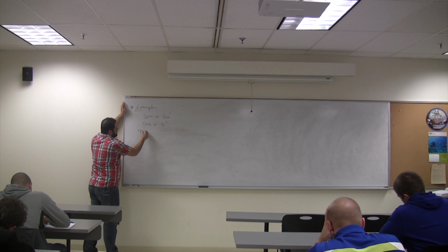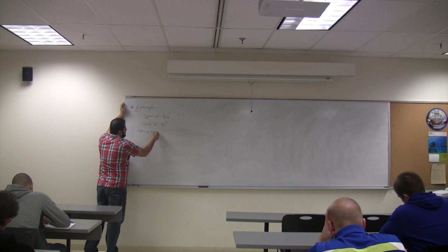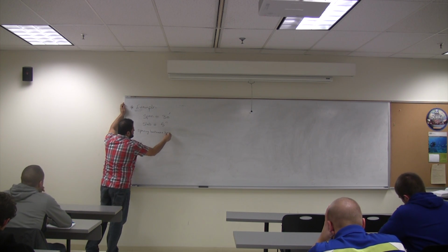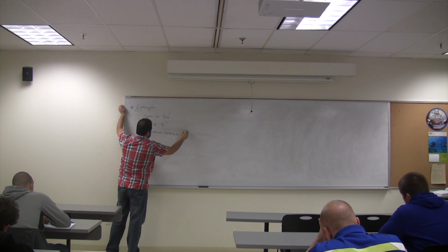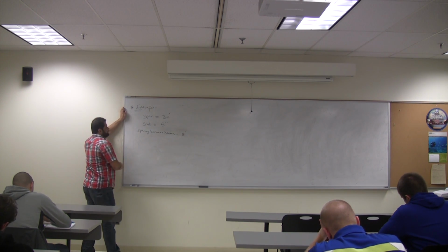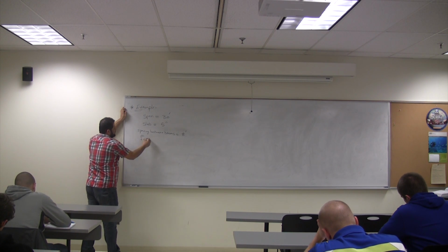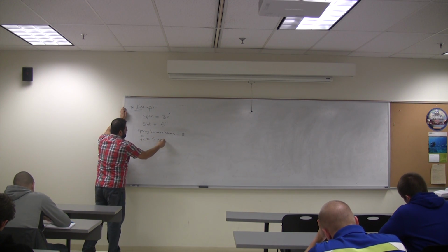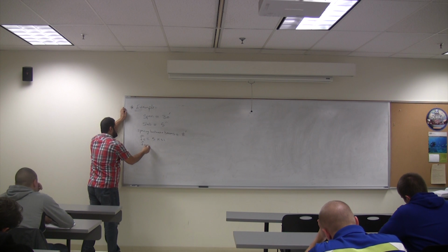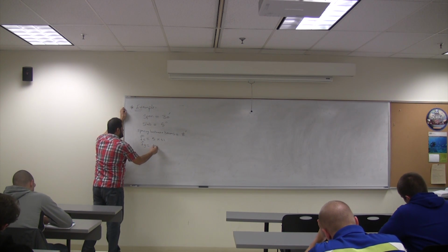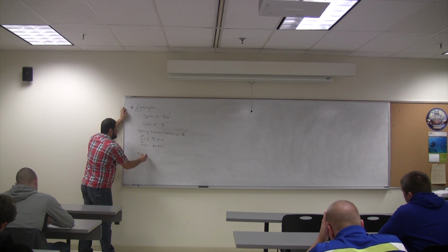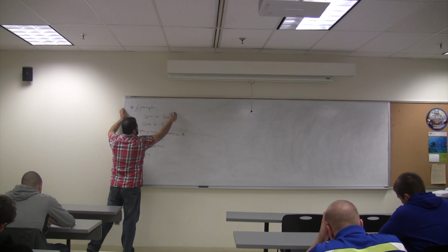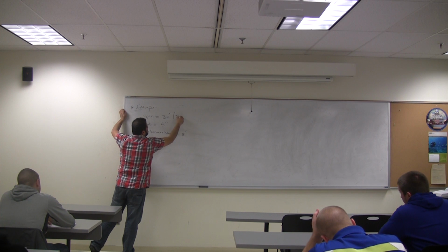Spacing between beams equal 8 foot. f'c equal 5 ksi. fy equal 60. Simply supported beam, span 30 foot.